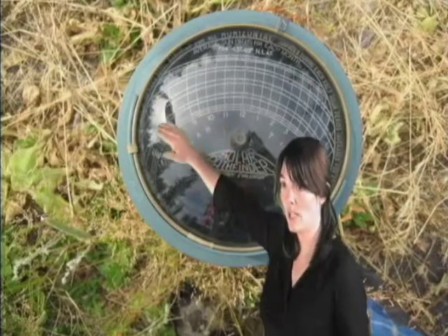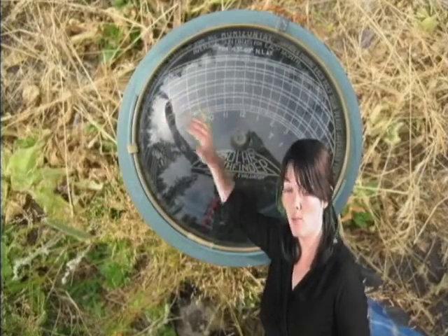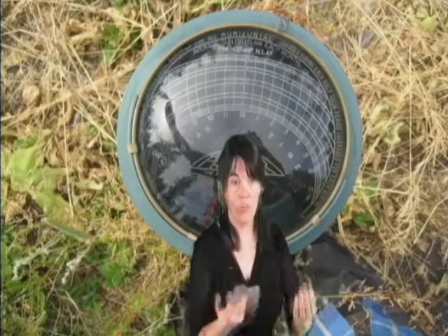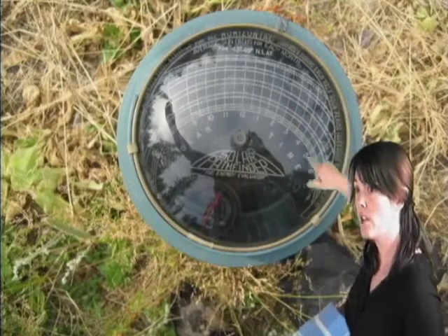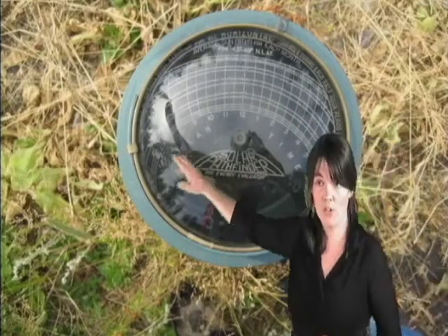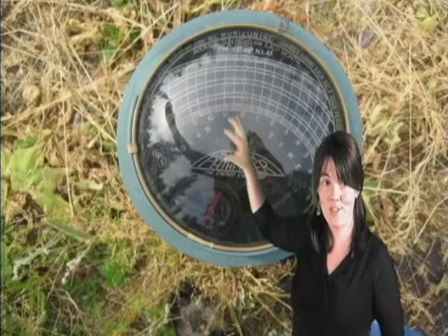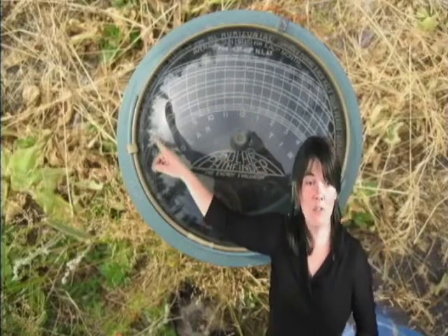Okay, so this is a pretty fun gadget. It's called a solar pathfinder, and basically it is a curved reflective surface in which we can see where things are going to hit. You take your solar pathfinder out, you stand in the spot where you would ultimately like to have the solar panels, and then you can see the shadows, and it gives you a 365 view. It also shows you, at different times of year, based on where the sun is going to be, where those shadows are going to fall.